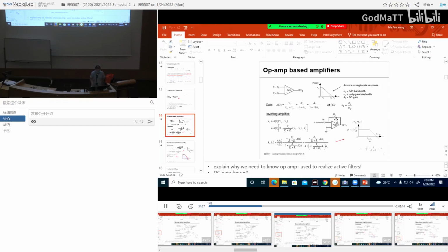But now you have a real op-amp with a real gain. But we still apply the same equation now. 0 minus this voltage, which we will call V minus or whatever, right? 0 minus V minus is the voltage across the input of the op-amp, multiplied by the gain, is equal to the output.